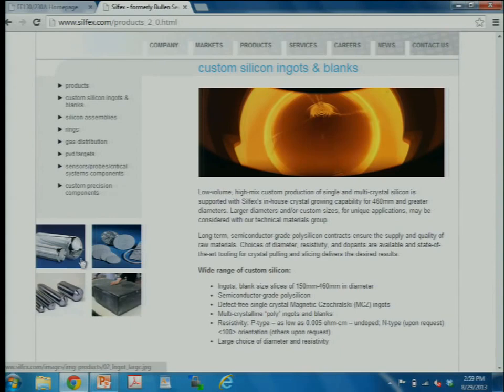Basically, you have this one huge single crystalline silicon ingot from which you cut slices, and all the atoms are lined up precisely with each other. That takes a lot of time, and it's more expensive. A bare wafer without any integrated circuits formed on it is several hundred dollars. With evaporation, you don't bother to line up one atom here on the substrate with one over there, because it's all just sprayed at once. There's no way you can guarantee that an atom here eventually will be perfectly lined up with an atom somewhere else.